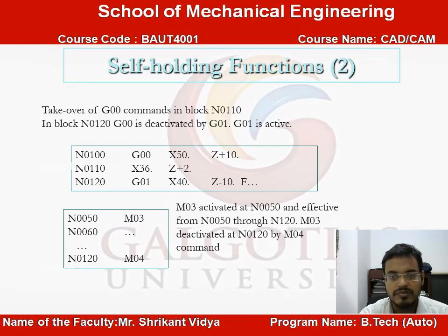In the same case, suppose in the next block N0200 you are writing G02, then G01 will be deactivated and G02 will be active. Similarly, if you go for G03 in the next block, then G02 will be deactivated and G03 will be active. In the same way, M03 is activated at N050 in the second block.